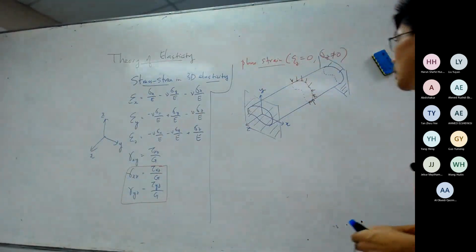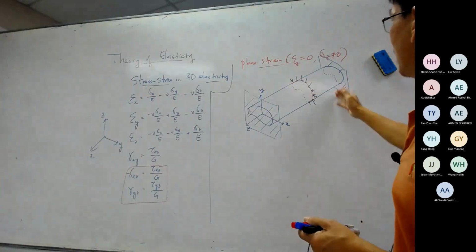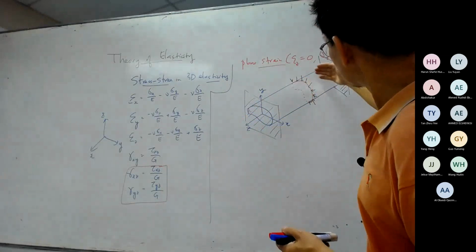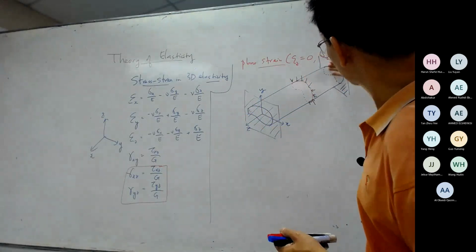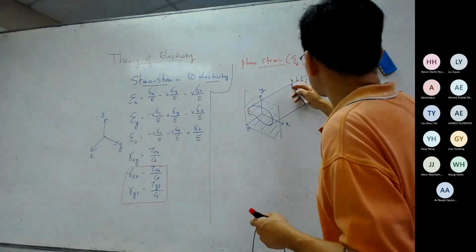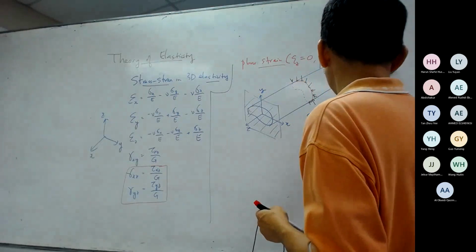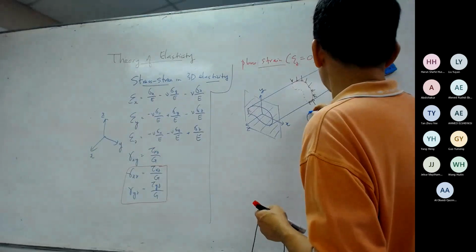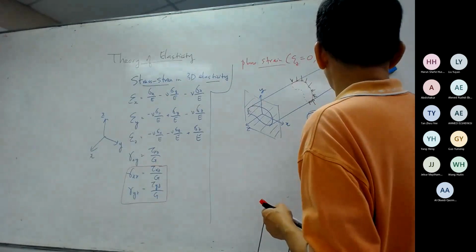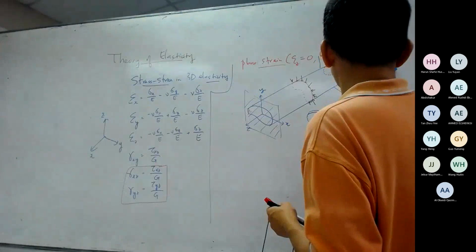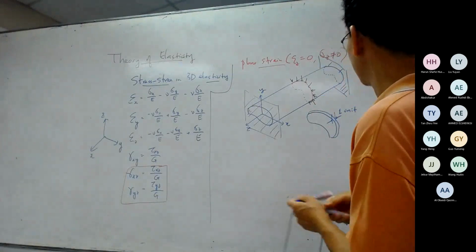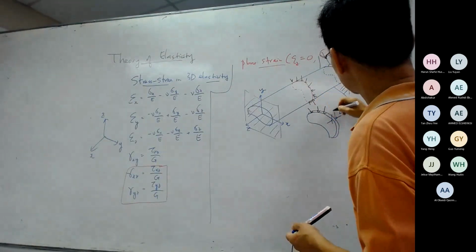We solve the plane strain problem because the geometry is the same from one side to the other, and the loading is also the same from one side to the other. So we solve this by taking one slice out of this, which becomes 1 unit length subjected to loading.